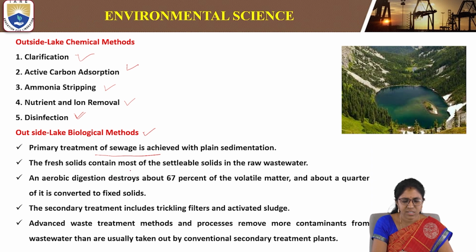The fresh solids contain most of the settleable solids in the raw wastewater, and anaerobic digestion destroys about 67% of volatile matter, and about a quarter of it is converted to fixed solids.